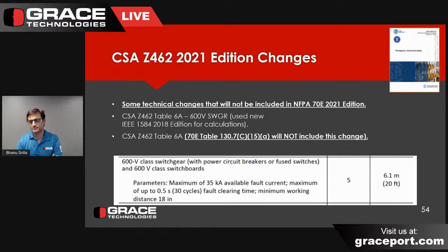You really can't. So we had the ability, and we took a look at the new 1584, which has significant new formulas. Some of the parameters are the same, but there are some new parameters that have to be very carefully reviewed, and should be reviewed by the consulting engineer with the owner of the electrical equipment so the owner understands. Again, this comes back to my comments about the quality of engineering reports, both in Canada and the US, where the engineer now needs to explicitly communicate with the owner on what they're doing and how they're selecting parameters.